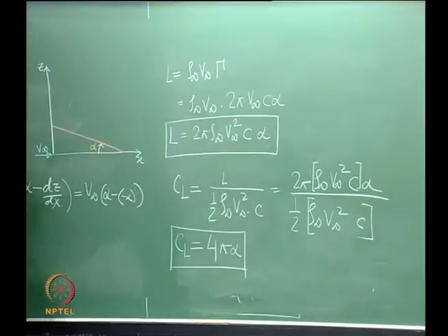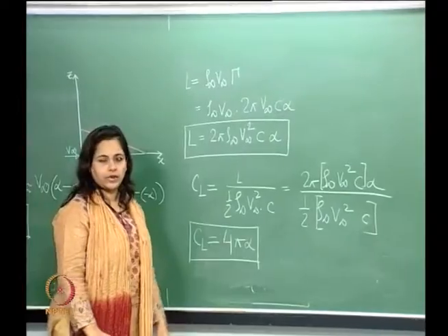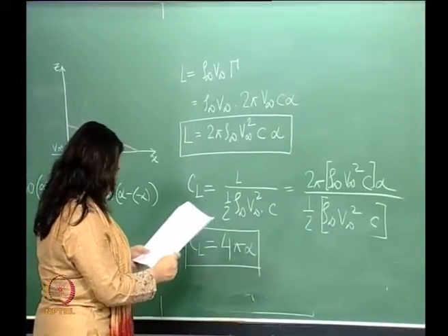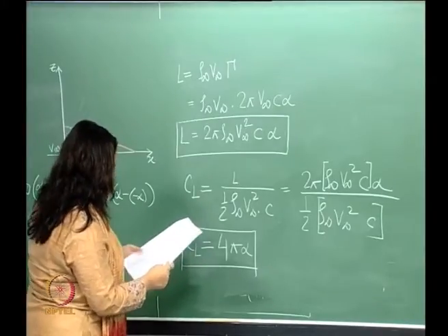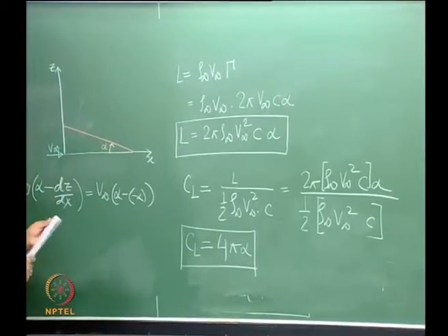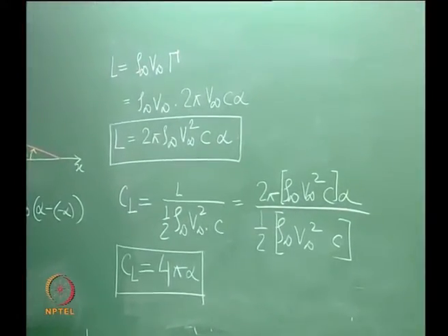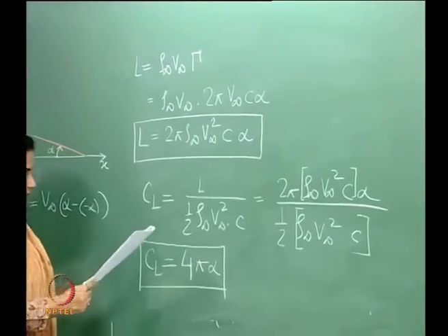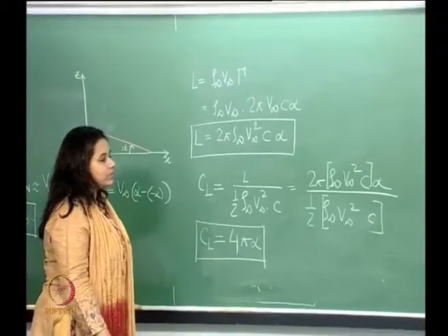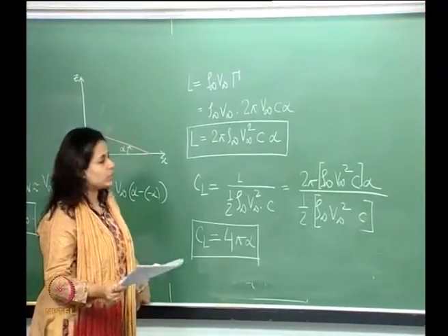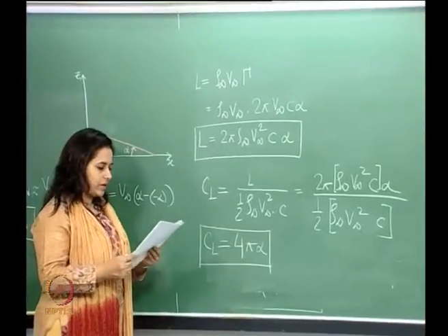Okay. So, the CL out here using the linearized theory is 4 pi alpha. Okay. So, this is our CL, right. So, now we will calculate the CD and CL for the Mach number here, which was a supersonic Mach number. It was just M infinity, right. We need to calculate that.